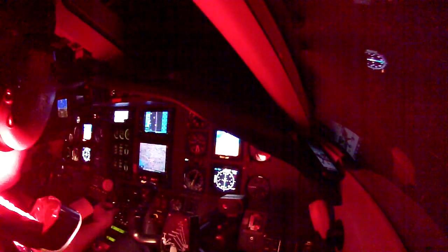So you can still use this plus the autopilot? Absolutely. If you are on localizer and you select the frequency here, and you select the localizer inbound course here, and you select nav on the flight director, it's going to lock up and intercept that course. When you select approach, it's more precise, and it's going to be in approach mode, and it's going to follow the localizer all the way down to the runway.